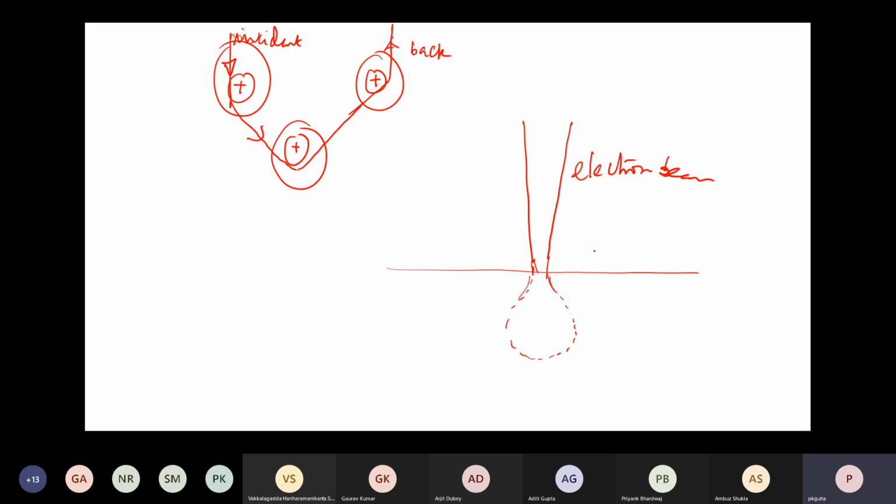Of course you can scan this electron beam to cover other areas, but this is known as interaction volume, the volume at which the electron beam interacts with the sample. As the interaction area and volume is more in the case of backscattered electron and X-ray, the resolution is less. Usually the secondary electron will come from very close to the surface, so maybe from this portion.